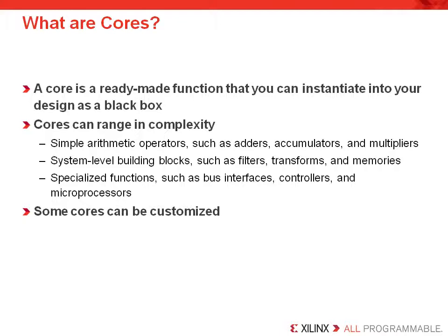Xilinx logic cores include simple arithmetic functions such as adders, accumulators, and multipliers. There are also system-level building blocks such as filters, transforms, and memories, and specialized functions like bus interfaces, controllers, and microprocessors such as MicroBlaze. Most of the Xilinx logic cores can be customized by the designer for size, speed, or various options.